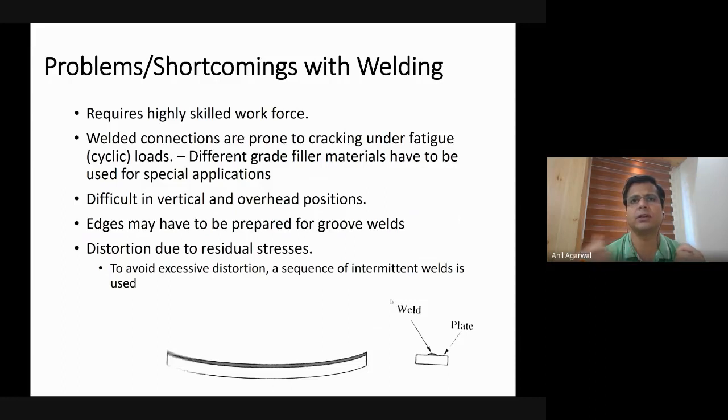They have to work for years and years to get that kind of certificate, because you have to be consistent. If you have to provide a weld of a particular size, say a fillet weld, right? If you stay too long at one place, let's say you are moving with the electrode along the length of the weld, you have to maintain a constant speed and make sure that you are covering the entire surface and depositing the same amount of filler material throughout, right? That requires a very high level of skill set, plus controlling the current and voltage for the requirement of the job, and what size electrode you are taking. So there is quite a bit of science involved in that as well.